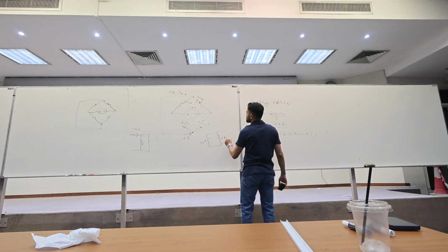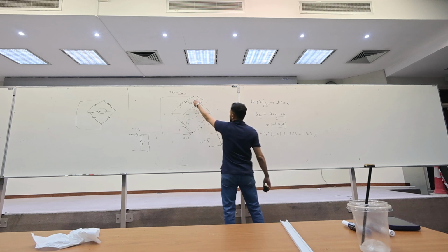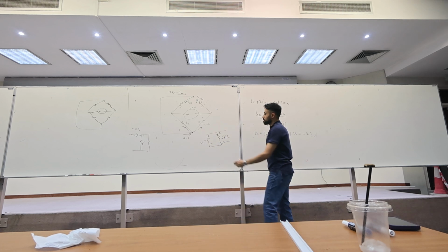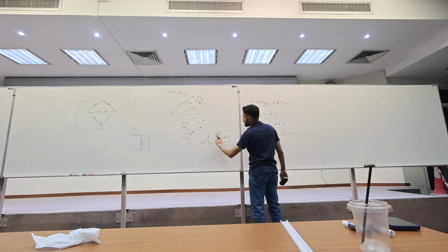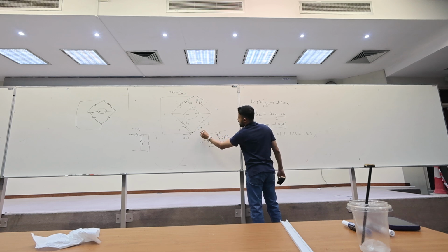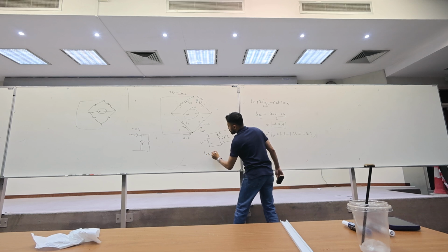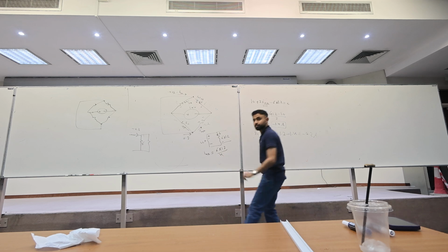It's 6 times 1.2, plus and minus. So I can know the current that goes through the 4 ohm resistor. If I know the voltage drop here, then the current that goes from positive to negative, which is I 4 ohm, I can know it. So I 4 ohm equals 6 times 1.2 divided by 4.